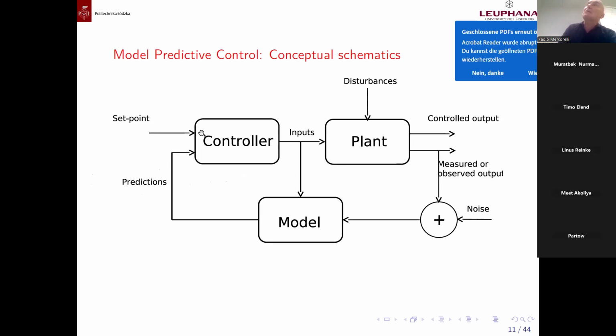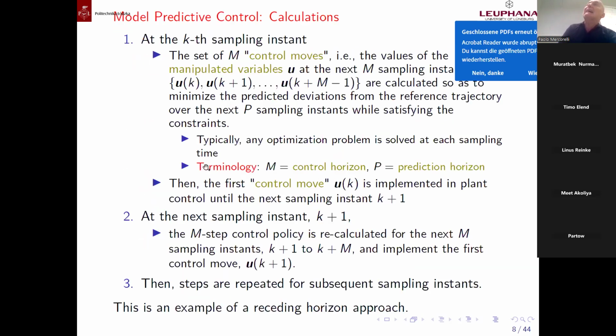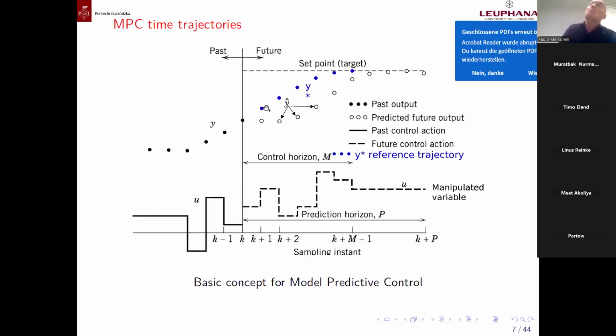The difference between what I want and what I have, also in the future, thanks to the prediction, we can see again here a little bit. For instance, tomorrow, the idea is to minimize this error here, because this empty dot is predicting. We can see here with the hat, we indicate always the prediction. And the idea is to calculate a U which minimizes this difference: what I want, the blue dot, and what I have, the empty dot, until the end of the control horizon.